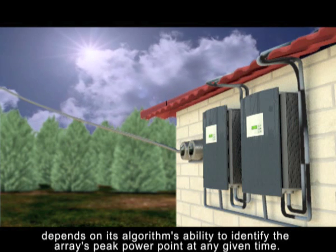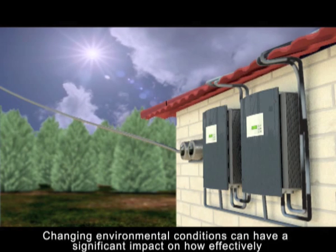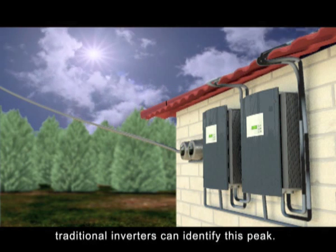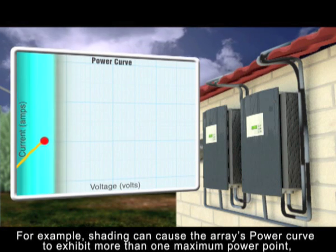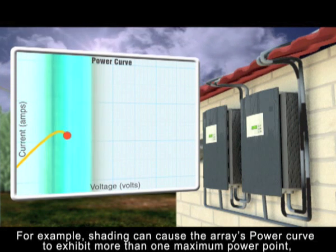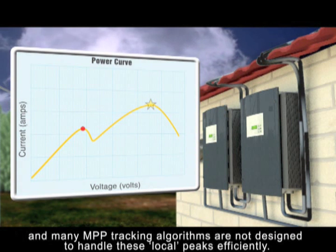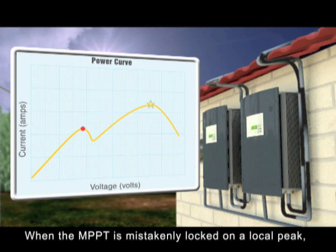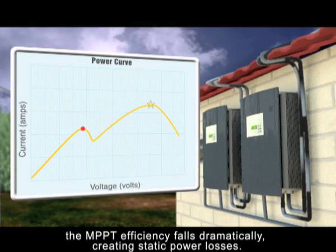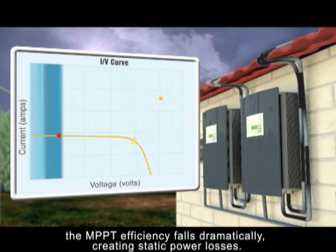The efficiency of the inverter's maximum power point tracking depends upon its algorithm's ability to identify the array's peak power point at any given time. Changing environmental conditions can have a significant impact on how effectively traditional inverters can identify this peak. For example, shading can cause the array's power curve to exhibit more than one maximum power point, and many MPP tracking algorithms are not designed to handle these local peaks efficiently. When the MPPT is mistakenly locked on a local peak, the MPPT efficiency falls dramatically, creating static power losses.